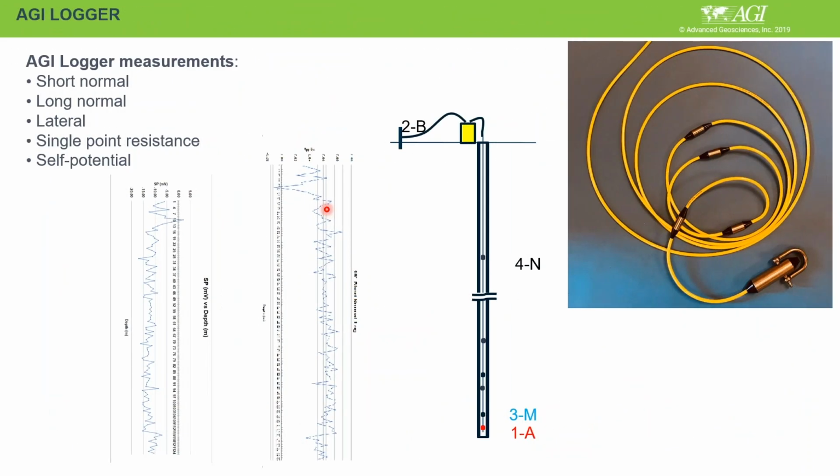He's asking about this borehole logging. Does it require special borehole casing? Okay, for the borehole you cannot use metallic casing, sorry. So you can use PVC, but that PVC has to be slotted, or it has holes.